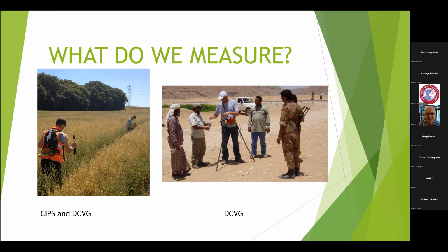And as he marches along the pipeline, sticking his reference electrodes in the ground, he measures the pipe to soil potential continuously. And the data is connected to an ArcGIS system, so that the GPS accuracy is sub-meter, and the data package comes with the date, the time, whether the system's on or off, and what the actual location is.